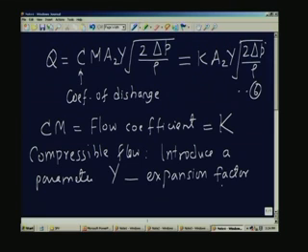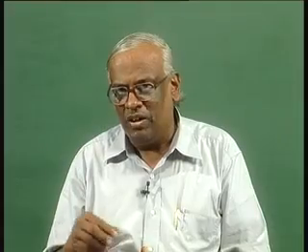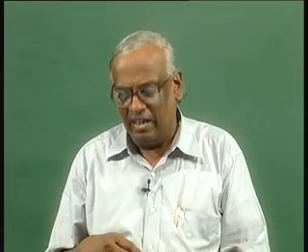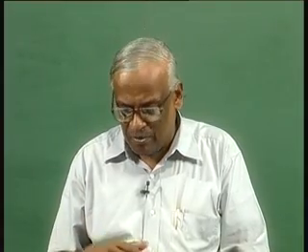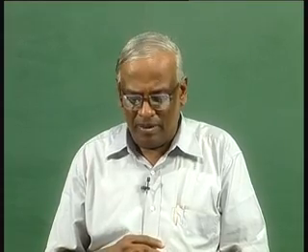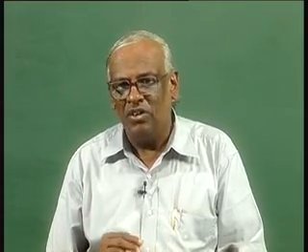This y is going to account for the small amount of compressible effect which may be present, because the velocity is not very small as compared to the speed of sound, in which case of course you would use the incompressible flow assumption, but small amount of compressibility is there, that can be accounted for by the factor y. Of course, later I will discuss about what this y is, how it is obtained, and normally what is done and so on, that we will come back to later. But basically the variable area flow meter, the operation of that depends on equation number 6.